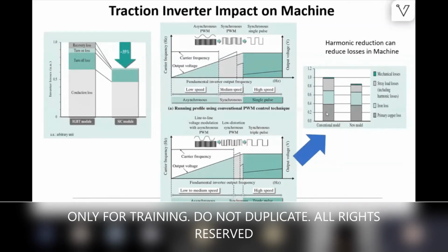You can compare these two, one with SiC and the other without. There are other challenges with SiC: because these devices are fast, they have more di/dt, so there will be insulation stresses on the machine. We have to consider the high voltage stresses due to the high switching speed, because the ramp-ups happen in microseconds and di/dt will be very high, so we will have voltages accordingly, and the creepage distances and all of those we have to address when we adopt this. But it gives significant advantages.